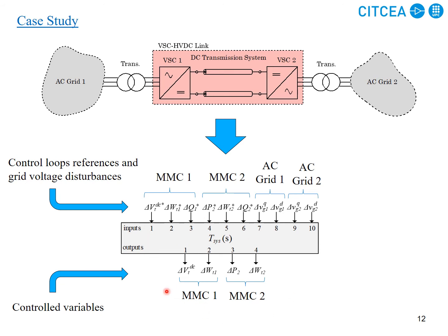But the references here, because of the cascaded control system basic rule, should be at least 10 times slower. So they are 10 times slower than the inner loops, and their dynamics could be more important in the system, more influential. But also notice that here is the control variable and here is the reference for this control system.